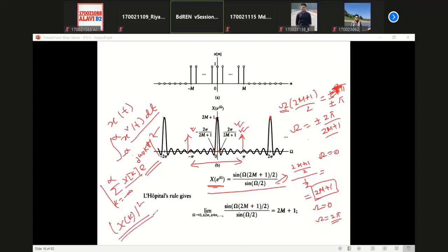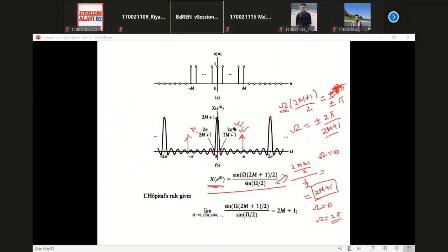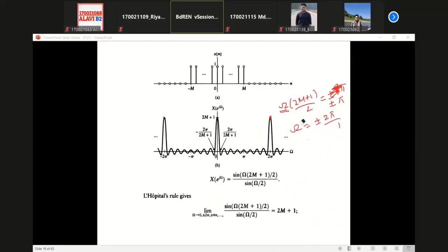So the square of the Fourier constants that we determined earlier is also related to energy. And if we express a signal from one form to another, after transformation the energy of your signal must be conserved, isn't it? The energy must be the same. This is an important theorem called Parseval's identity. We will discuss more about it afterwards, okay? But in this case, using this energy conservation, if we integrate from minus pi by 2 to pi by 2, as we can reconstruct our signal, then the total energy of the signal can also be extracted.